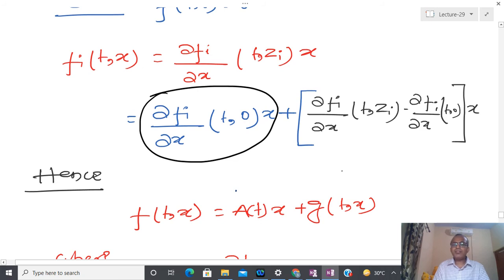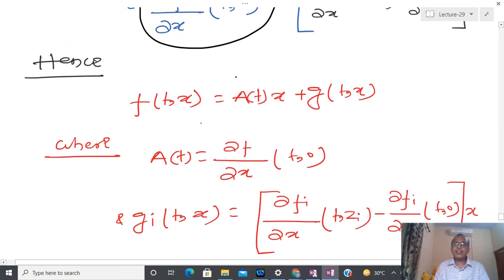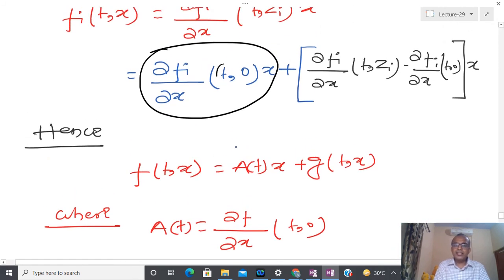Okay, and after that, now here in f(t, x), if you calculate the Jacobian matrix of this, then time is also involved, and due to that reason this is no longer independent of time. Time dependency comes into the picture. So now after linearization of the non-autonomous system, I will get some kind of LTV system, linear time varying system, as part of this.